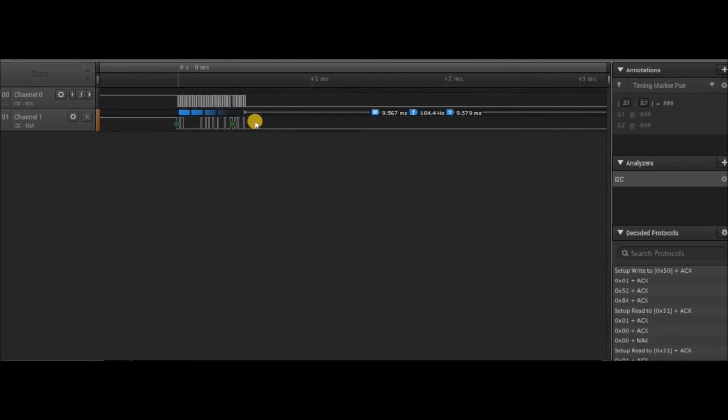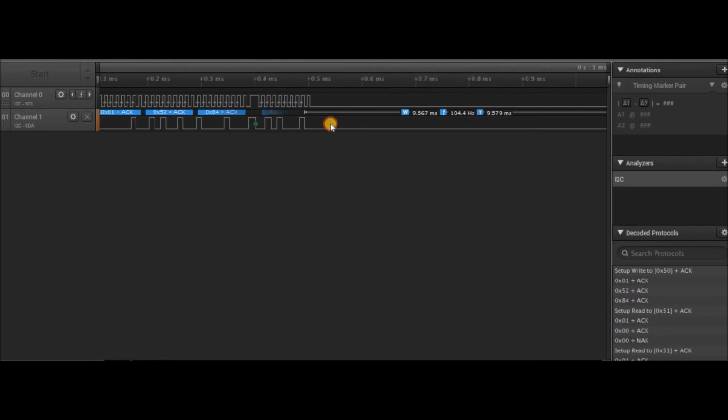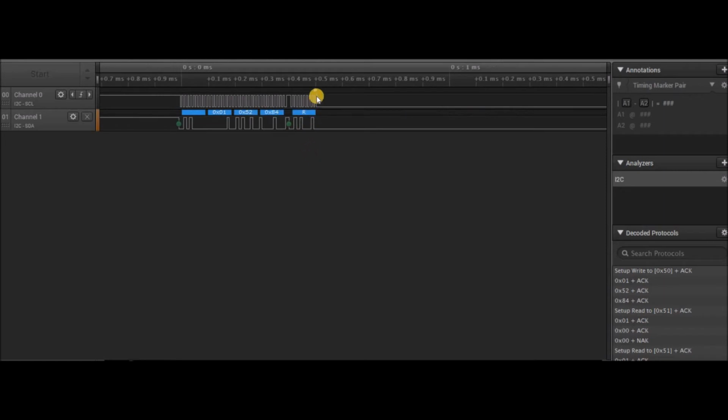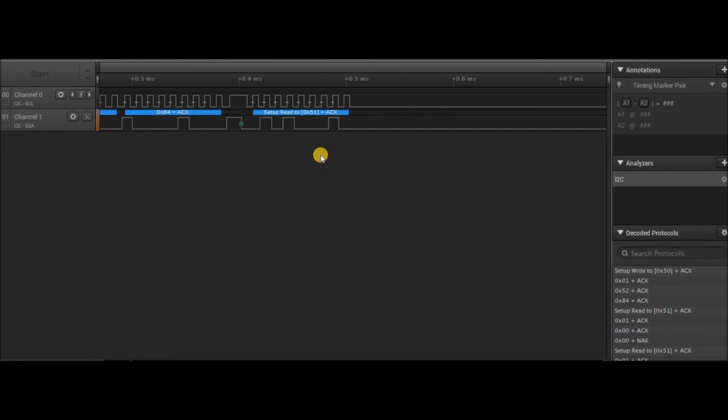Well, the fact is that when the slave device on the I2C bus cannot respond to a message, here it cannot respond to the read taking place because of the fact that it's in the process of executing the command, which was to start deleting the flash. Deleting the internal flash takes a certain amount of time, and during this time interrupts are blocked, and the behavior of the I2C slave is that it does something called clock stretching.